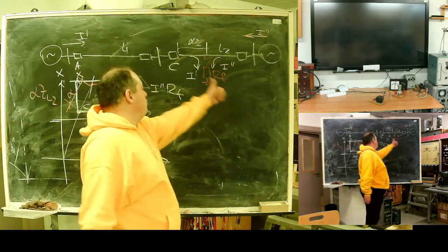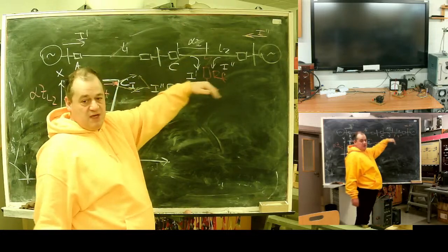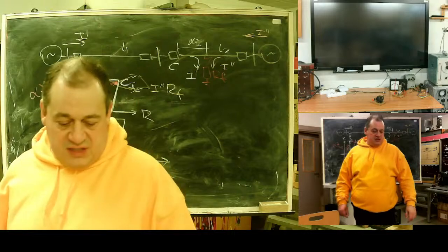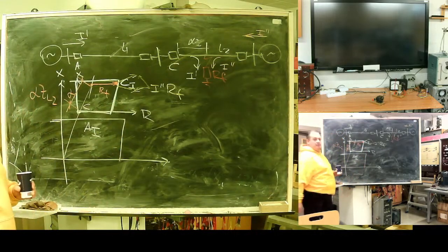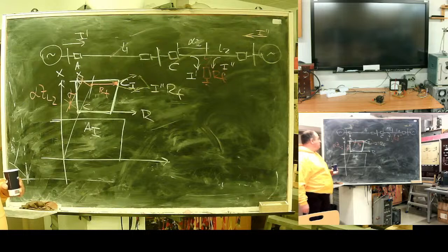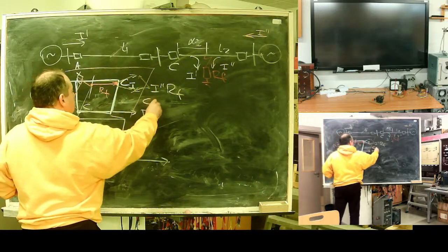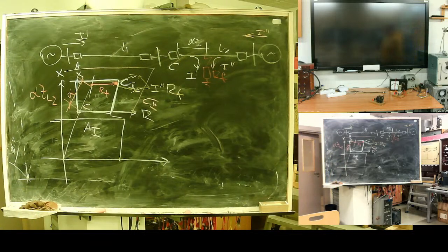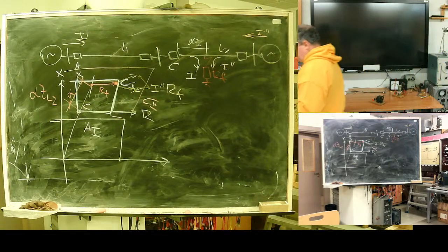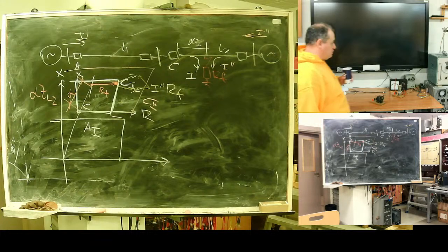It should be calculated. It can be well predicted which way it goes, up or down, but in most cases, if you have transit from the second system this way, it will go up. If you have transit this way, it will go down. But again, you need to take into account resistance of the system. You need to calculate. Anyway, will protection operate here? In only first zone? No. It will be C2. We will see operation of the second zone instead of first, as a result of the current from the opposite side. It's a problem of distance protection.